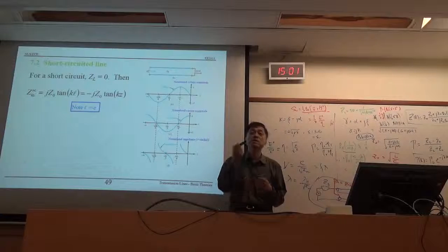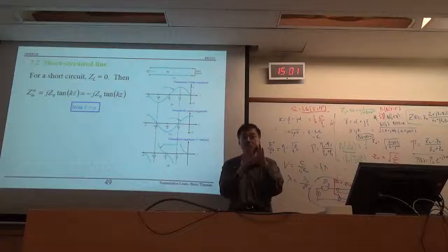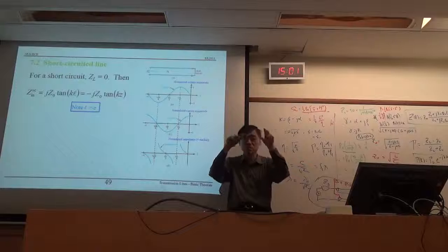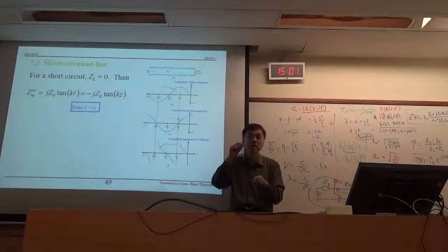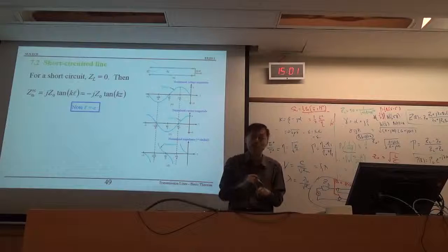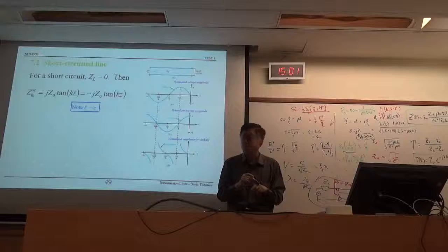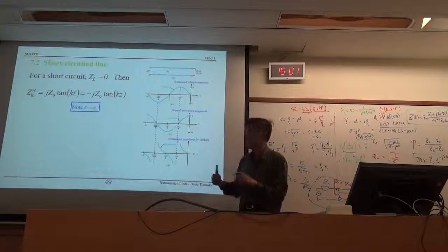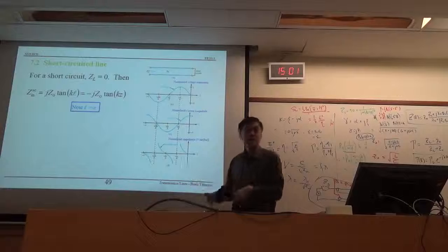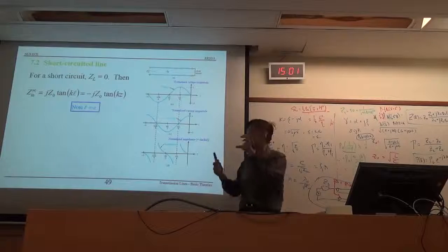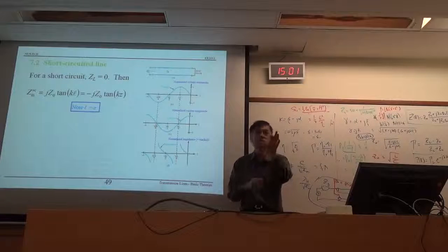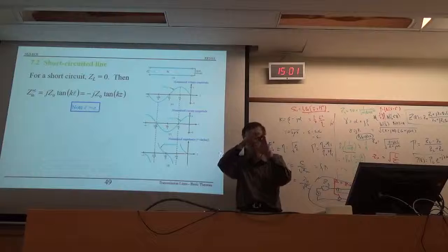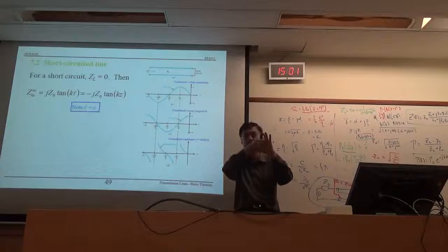But what is the length of the connecting wire or bonding wire? You want to bond this cabinet to ground, or you design a circuit and want to ground it. What is the length of the ground wire, and what is your frequency of operation? Remember, the length is measured in wavelengths. If your grounding or bonding wire is exactly a quarter wavelength long, then you are not grounding. No matter how thick the wire is, you can have a big thick strand of wire.